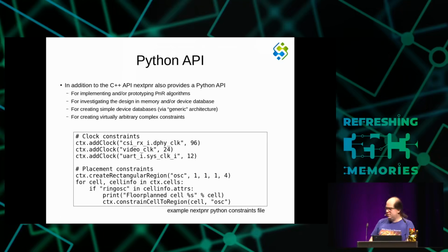I think that this is much more flexible than other approaches, especially if you have larger designs and constraints where it's really hard to explicitly write a list saying this should go here, this should go there. Instead, you would like to have a small program that just looks at the design and then extracts the placement information from other hints that are already there, using things like cell attributes or just hierarchical names of objects in your design.